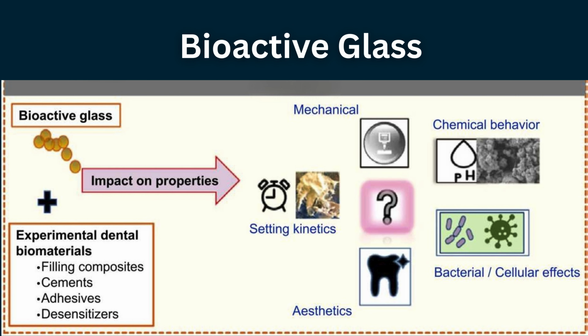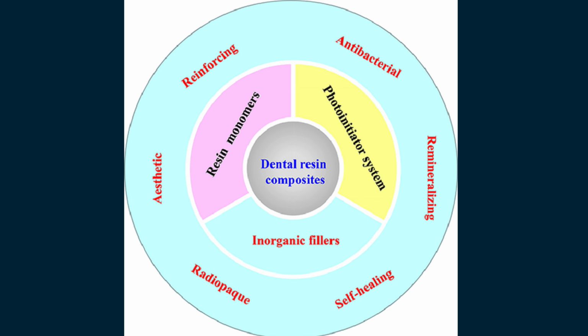Phosphate-based glasses represent another class of bioactive fillers capable of controlled degradation. They can be doped with metal oxides such as copper oxide to impart antibacterial properties. However, filler particle size must be carefully controlled. If particles approach the wavelength of curing light, they may reduce the degree of polymerization of light-activated adhesives.